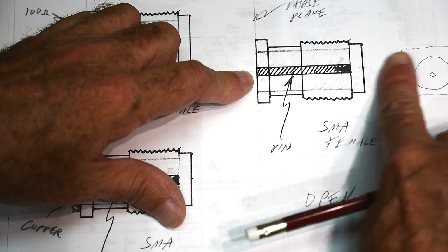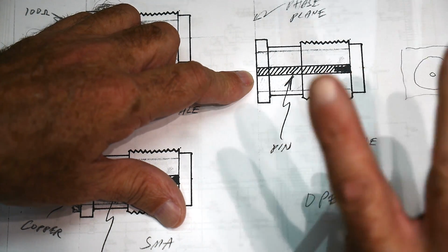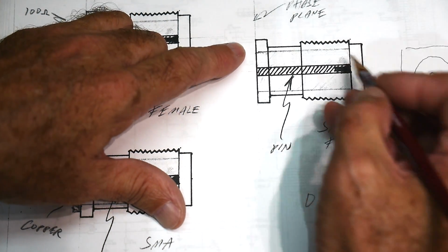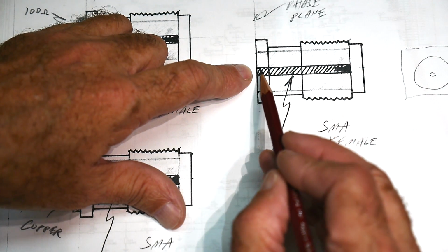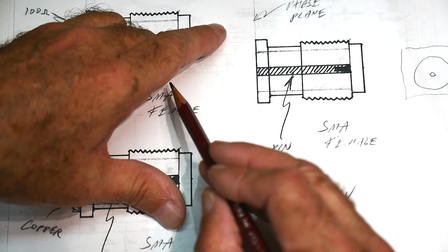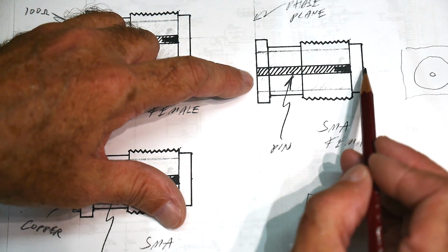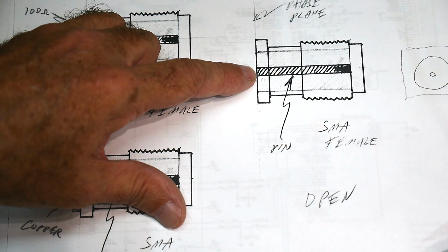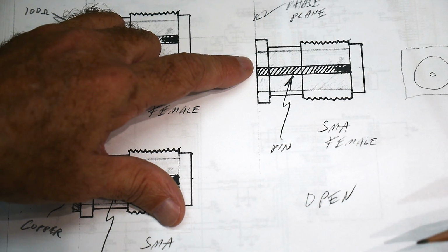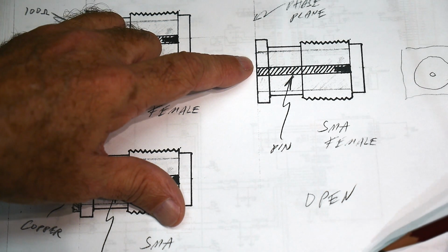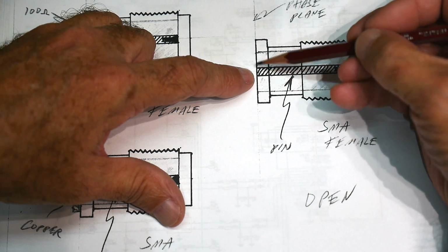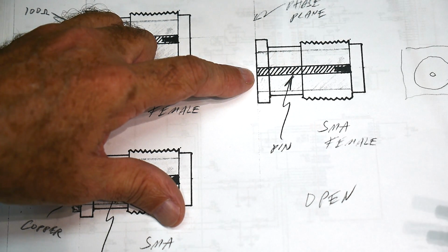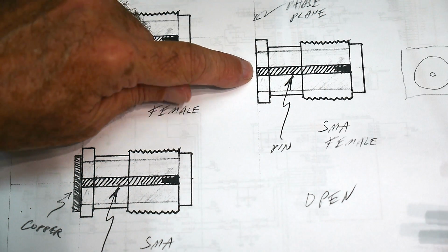And so I just made sure this was all flush, and that's my open. So the electrical signal will come down the center conductor, the pin, and it will come to here, and then it'll see nothing, and then it'll go right back the way it came, and it'll stay in phase. Right? So that's the open. The open is really, really easy to make. Now, what does that mean? It means that there is some place where phase is 0. And that place is right where this reflection happened. So we're going to call that the reference plane. Okay? So right here is the reference plane.